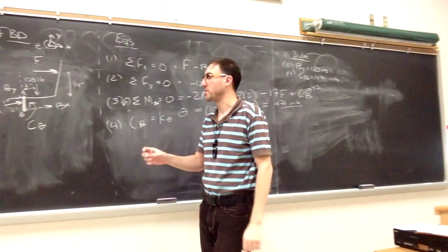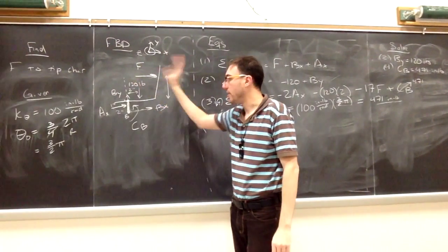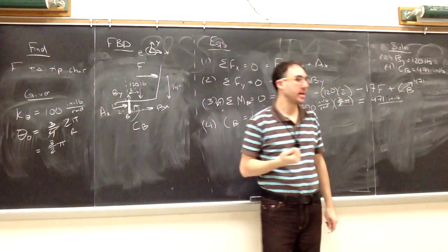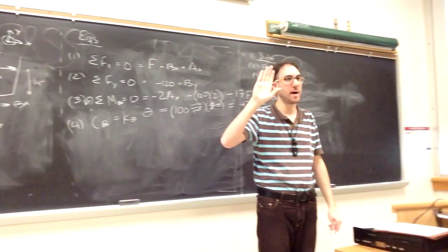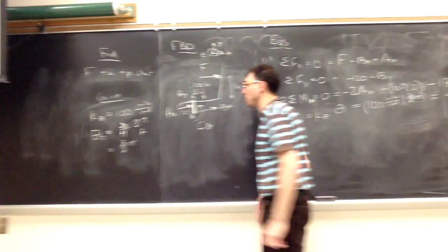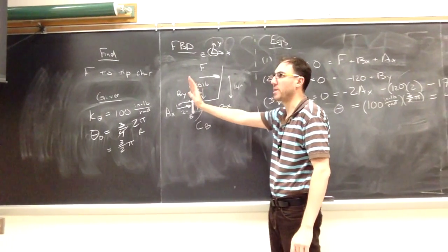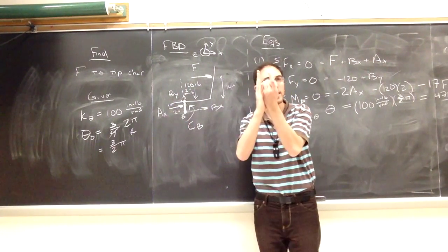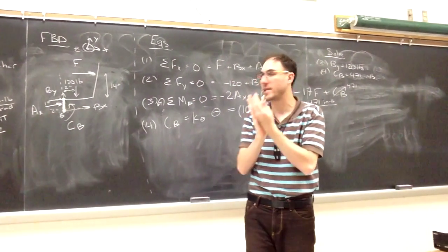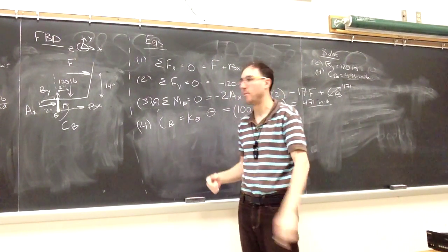AX, that normal force, the picture doesn't know that I'm looking at it when it's about to lean back. But if I'm looking at a situation where the chair is just about to start to lean back, that means that the contact force between the stem or the post and A, as soon as it loses contact, is going to cease to be a force there because, again, it can only push on it, it can't pull on it.